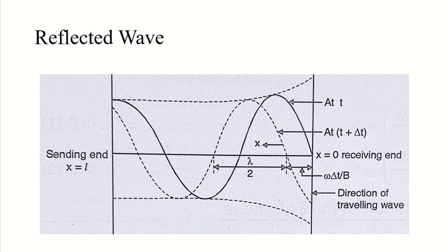We can get rid of it by placing a steel conductor at the center, with the other conductors around it coated in aluminum. No, sorry, the central conductor will be an aluminum core, and the other conductors will be steel. We can even do the alternate, right? We can even take steel in the center as well, and strand it with aluminum in a twisted shape. So we can do that too.